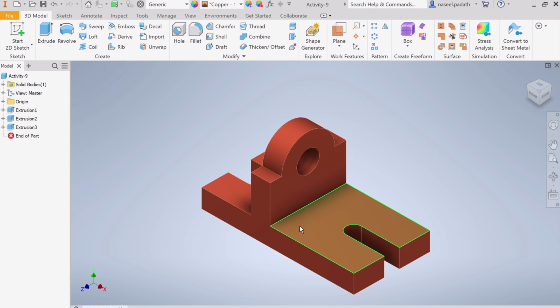So here we learned many things, especially how to manipulate this kind of shape by choosing different planes for various sketches. Let's go through the activities that we did on the model tree. First, we extrude this side profile and create it from the vertical plane, and then we create these sketches to cut the holes, and finally we create this one and cut down the corners and create a hole in the middle. So this is how we create it.